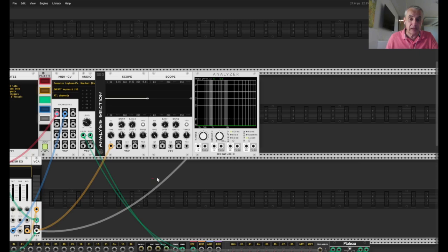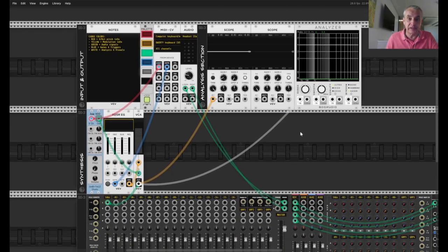So how can you avoid aliasing if it's really necessary? Well, again, going back into theory, any signal that is not band limited, i.e. band limited means that there is a maximum sine wave frequency in all the collection of the harmonics of a particular wave, but has actually an unlimited amount of different sine wave frequencies, you cannot reproduce it. Whatever sample rate you're using, there will be aliasing in some way, shape or form.